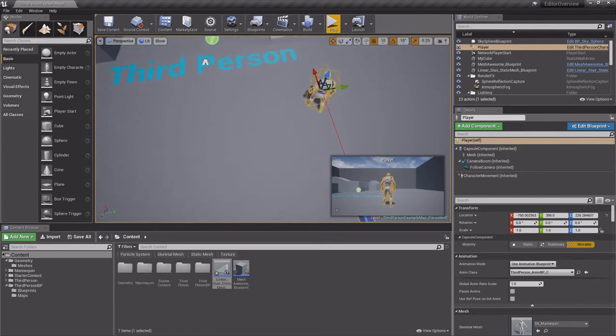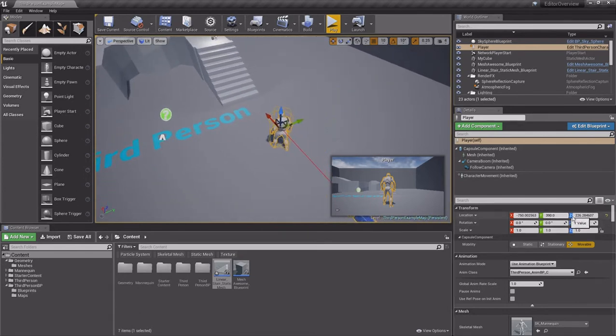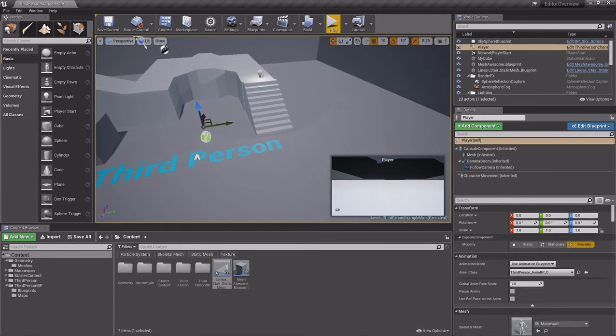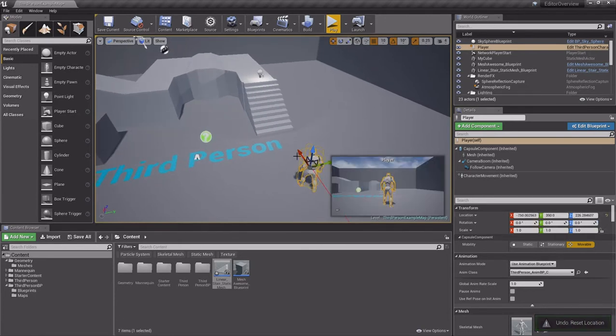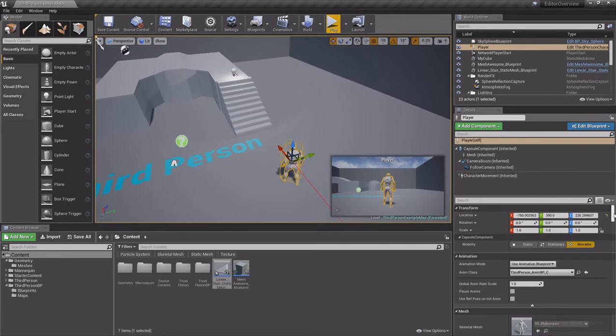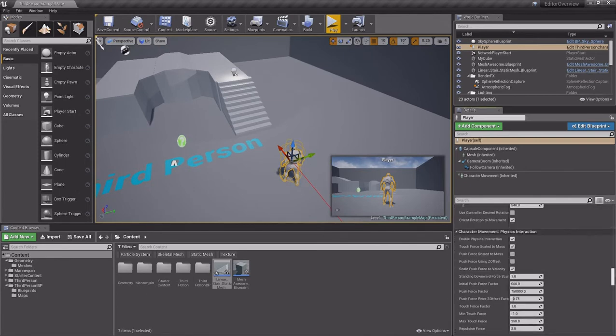Now, how do I know that? Well, the location icon over here, this little reset to default icon, is showing up. It's a little yellow backwards arrow. If we click on it, it'll reset it to the defaults. In this case, 0, 0, 0. I'm going to undo that, put it back to here. Anything that's been changed, you'll go ahead and see that with that icon.